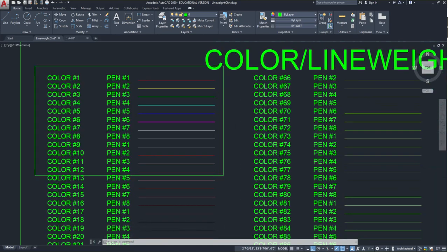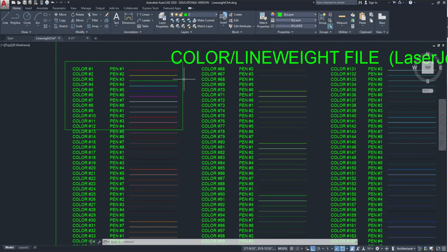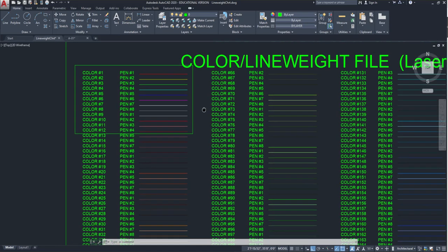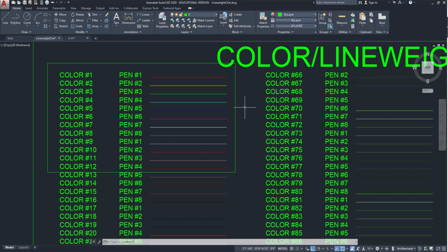So, you look at this and you say, well, it looks like pen number 6 is the heaviest here. Why can't I use these green colors instead of this red color, right? And the answer is you could, okay? You could. They really do illustrate the same thing. But it's not very standard, meaning if I were to go into an office, I could open up their layer dialog box and I would see red, yellow, green, cyan, blue, magenta, and I would know what that means, okay?